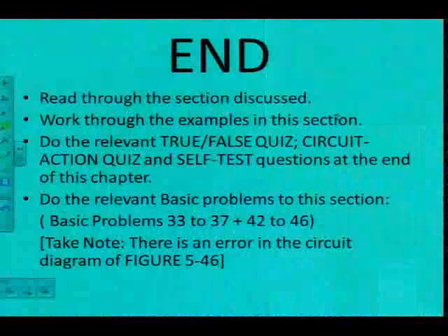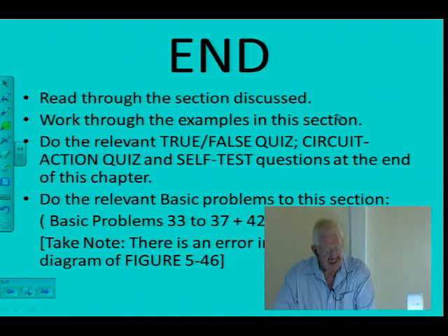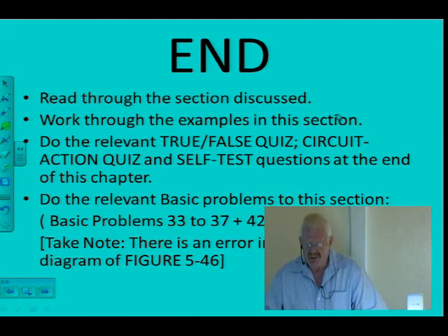If you read the question, it says that there's a PNP device. With a PNP device, I would expect negative voltages, especially like in the example I've shown you in the previous section. So make sure when you do your calculations that you get negative values, and don't be confused by this method of measuring to get positive values. Alright, that concludes this section.